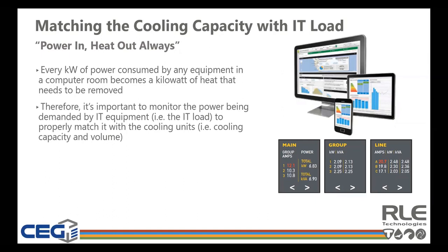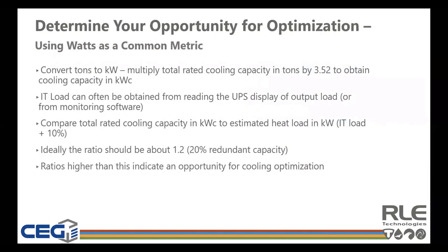So this includes all power conversion and distribution losses, as well as every kilowatt of electricity consumed by the IT equipment. So this is why it's critically important to match or exceed the cooling capacity to the IT load, and it's the role of the raised floor and the correct type, quantity, and location of the perforated tiles to distribute the necessary cooling capacity.